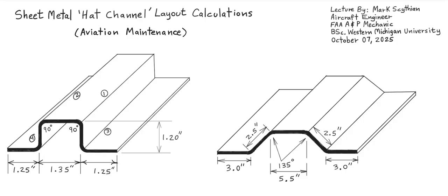So the first thing we have to do is look at the bend schedule here in black, and the sheet metal width is constant. So you'll have to break the sheet metal bend into components. So we'll break up the sheet metal bend into these given layout components.